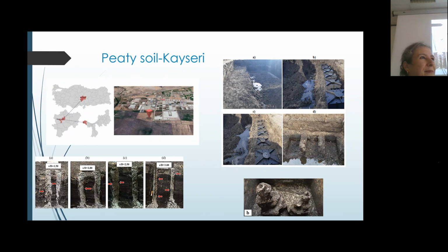The classical inorganic clays are generally characterized by very high damping at high strain, so they tend to de-amplify, maybe, in case of strong earthquakes. Organic soils are less dissipative, so they amplify a lot also in the high strain range during a strong earthquake. So it's a very peculiar behavior with respect to inorganic clays.